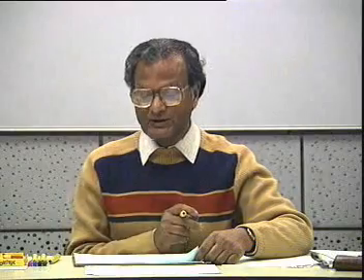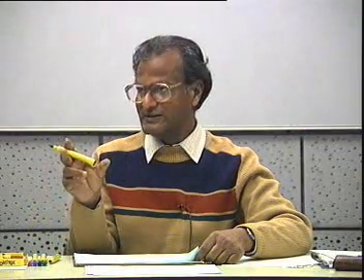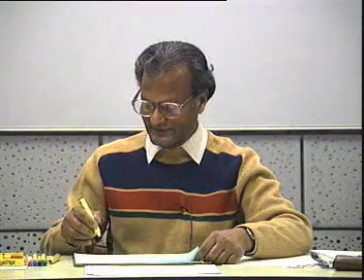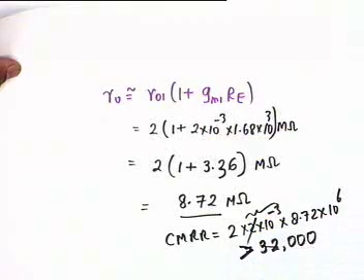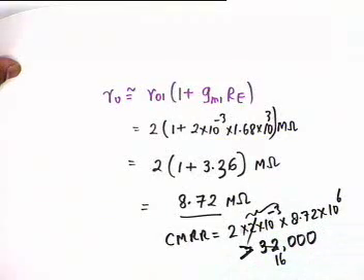Why? The current is coming from both. Because IC1 is IEE, and therefore each transistor has half of this current. Each main transistor in the differential amplifier carries half. Therefore, GM would be 1 times 10 to the minus 3, and this would be 16,000. Even then, the figure is very large. I am glad you pointed it out.